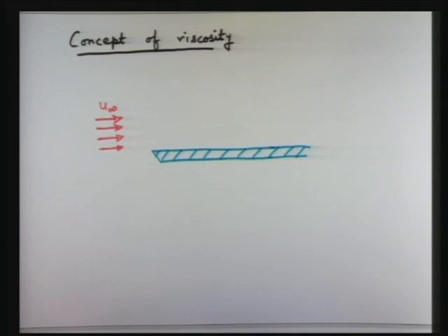For example, if two of us are walking and we are colliding, knowingly or unknowingly we are exchanging our momentum. So the fluid in direct contact with the solid boundary is exchanging momentum with the solid boundary. When this exchange of momentum is complete, then we can say that the state of velocity of the fluid is the same as the state of velocity of the solid, and that means that there is no relative tangential velocity between the fluid and the solid, which in a loose sense is known as the no slip boundary condition.